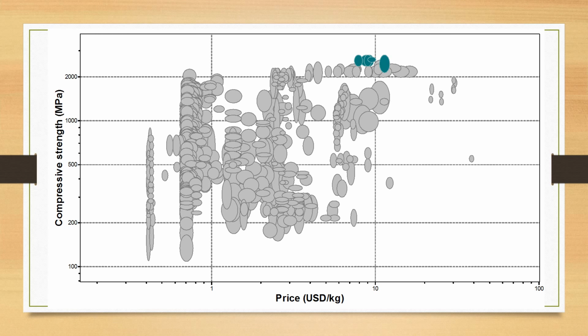The average retail cost of a commercial padlock is about $4 US, and taking into consideration a suitable profit margin, the cost of production of the average padlock should be about $2 US, and the average mass of the padlock should be about 100 grams. This makes the maximum allowable material price $20 US per kilogram, assuming the shackle and padlock are made from similar materials.